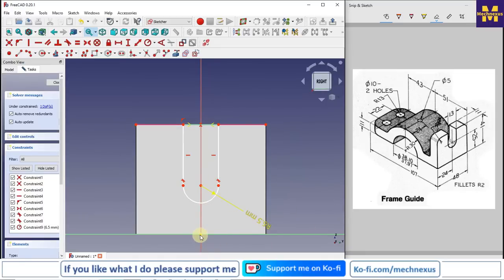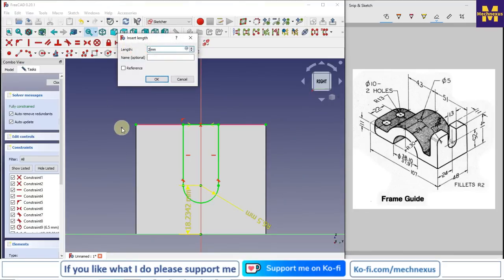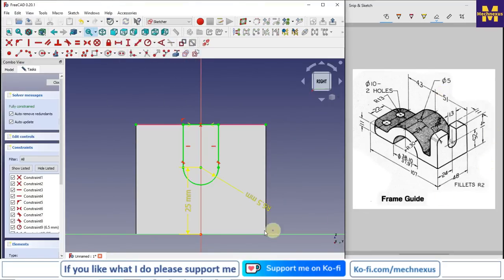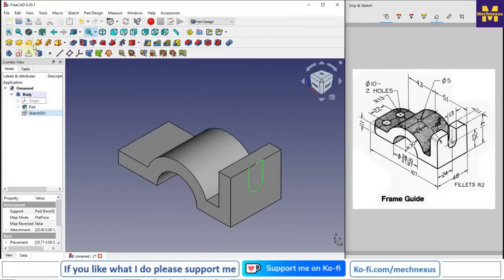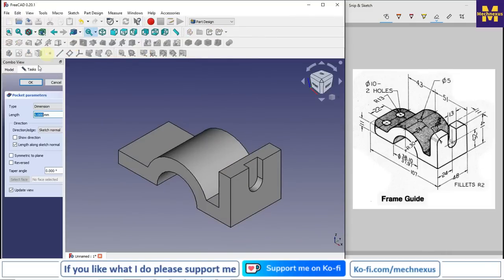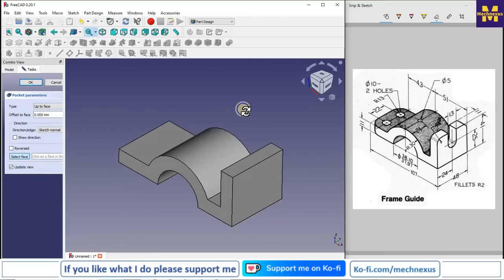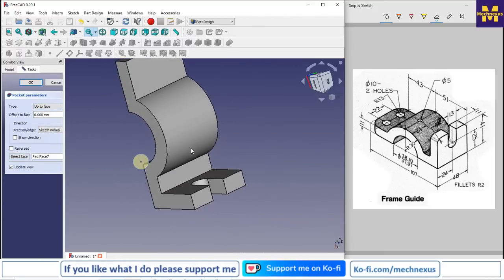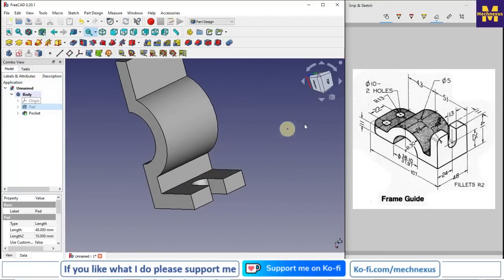So better I will give simple this dimension 25. So our slot is fully considered. Now I will close it and I will say cut, and here I will select up to face, and I will select this face, and I will say OK.